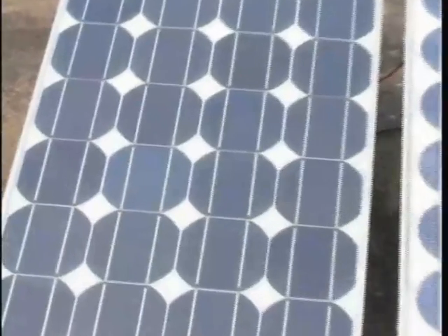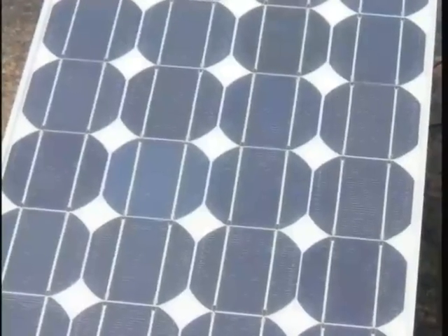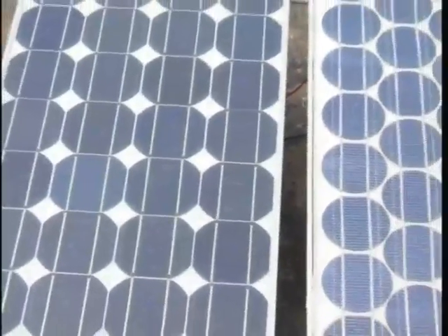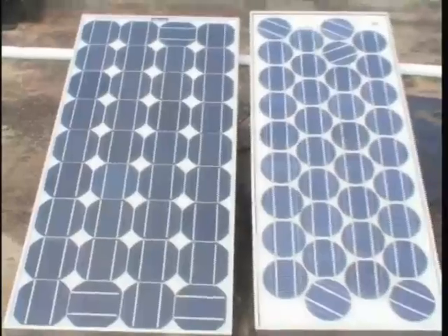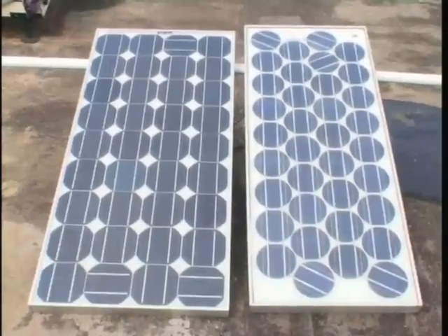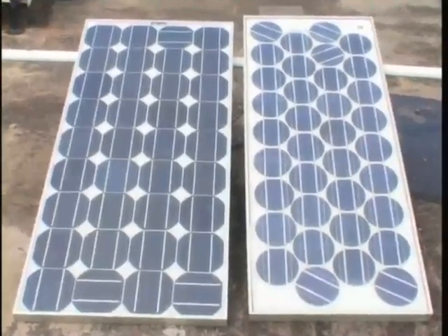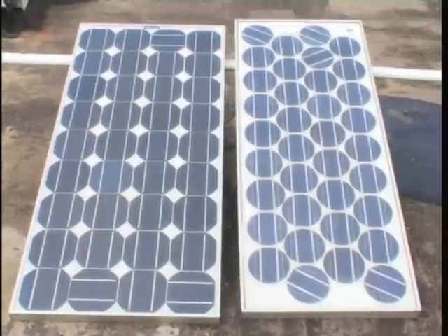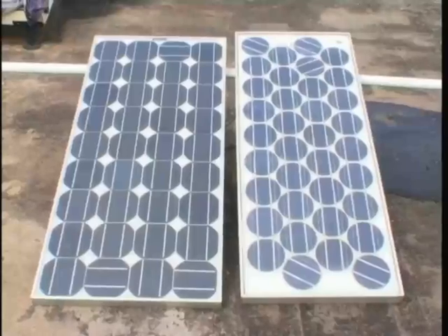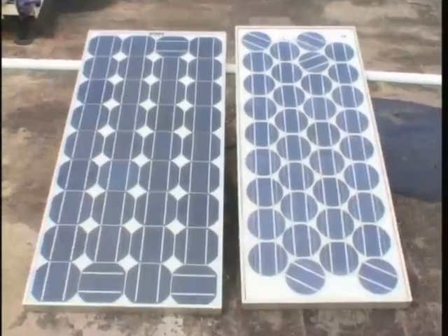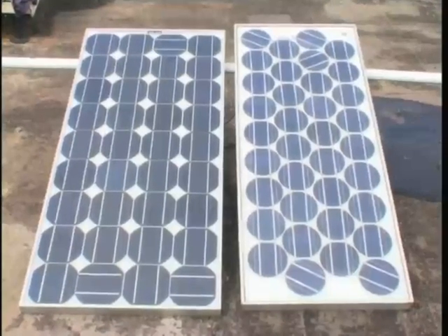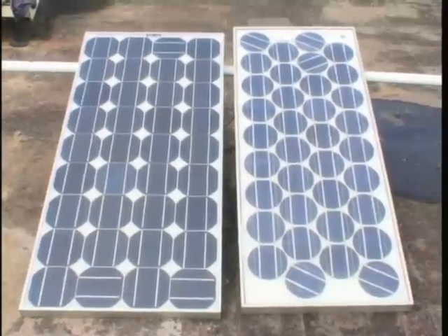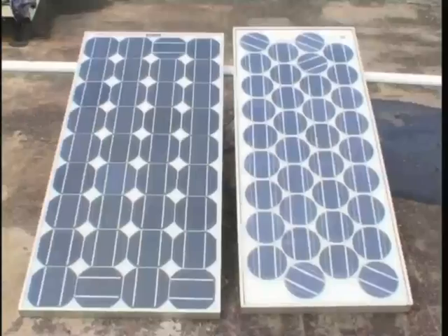These grids, as I told in the class, are later put over the surface by means of some kind of lithographic technique, screen printing like technique, and there are different designs of those top fingers in order to collect the charge. At the bottom you have a simple metal substrate on which the silicon is laid, and that metal substrate acts as the charge collector.